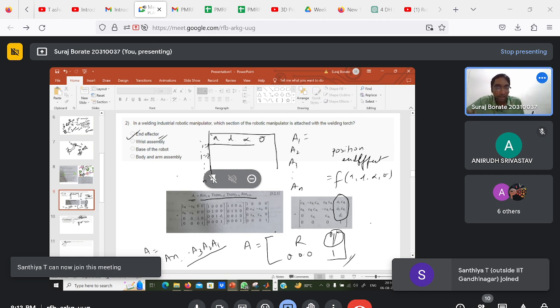That other method is when you have been given the 2 frames, and you have to find the homogeneous matrix between these 2 frames only, and the 2 frames are described by the unit vectors f1, f2, f3 and m1, m2, m3.